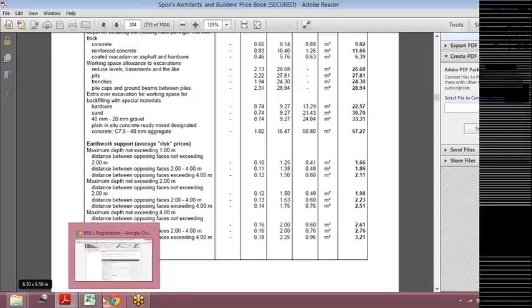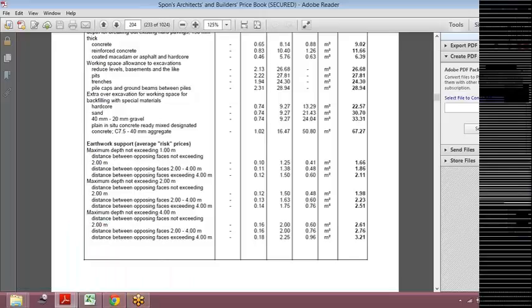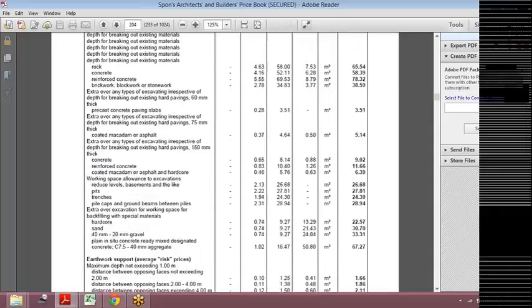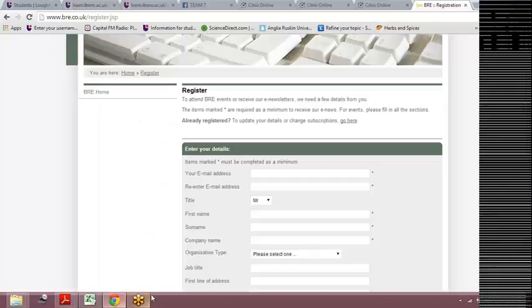Okay. So you can go to whichever book you want, and it basically has tables like these for earthwork, for electrical works, and for temporary structures as well. They have how many man hours you need to put in. So you just have to go through the book and come up with your duration.